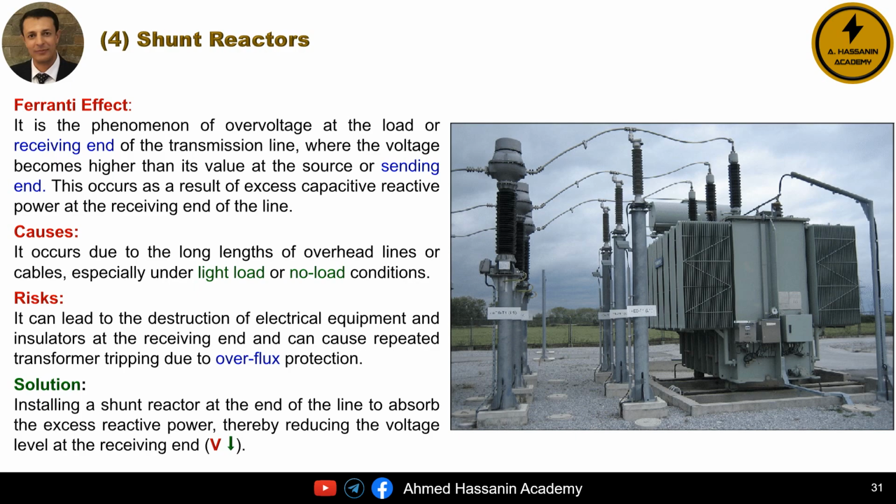However, we must also recognize some of the disadvantages of installing shunt reactors. One of the major issues is that we are dealing with a very large amount of capacitive reactive power, which means that the circuit breakers capable of handling this capacitive reactive power will be extremely expensive, especially considering we are operating at high or extra high voltage levels.